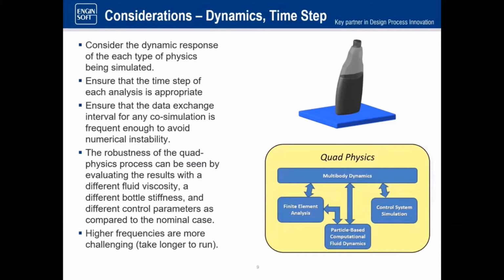But one should watch, in cases where you don't have the fluids, maybe you're just doing something with controls and some other kind of physics, it's important to make sure that you have a small enough time step. In the case of a control system, you can determine and set what that handshaking rate is, and just make sure that's sufficiently frequent to avoid the instability.